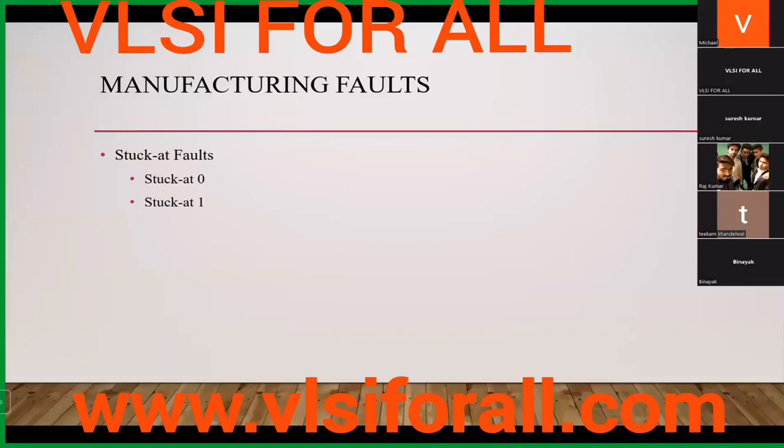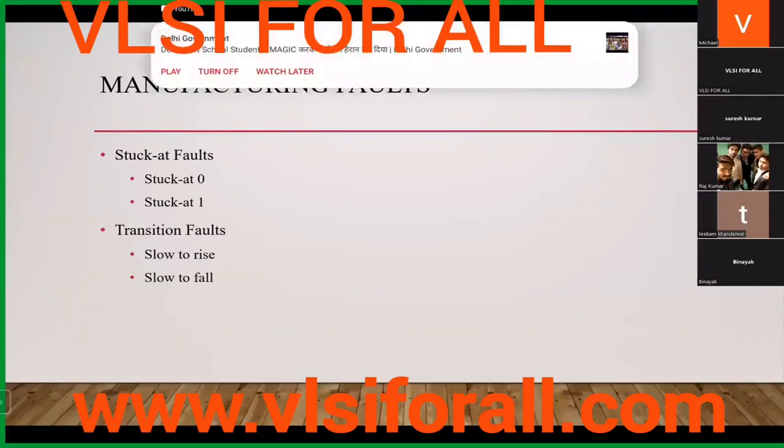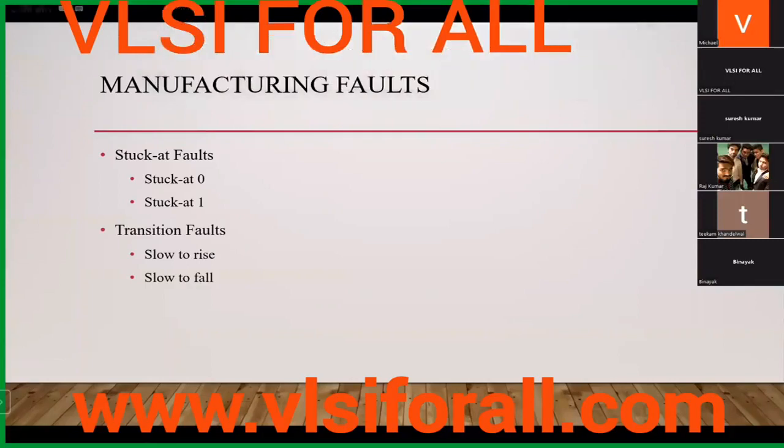So there are different types of manufacturing faults. These are very prominent faults which in industry we are checking. One is stuck-at, one is transition fault. Anyone knows transition faults? Yes, it's that delay fault, mainly in the delay category. So at-speed testing comes under it. We check that at a particular rated frequency, the node is rising or falling within the rated frequency range in the time window.